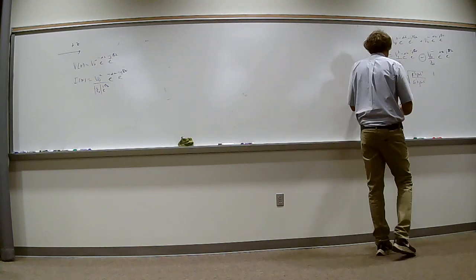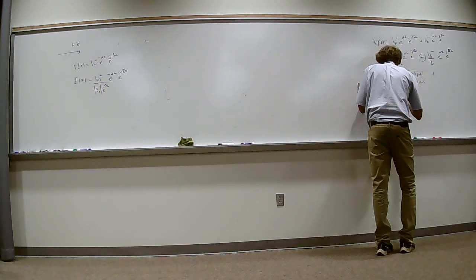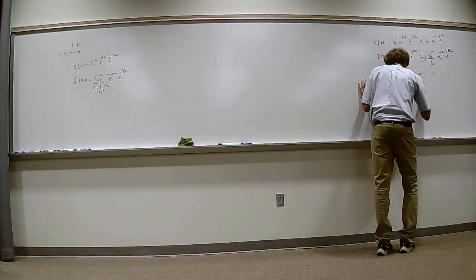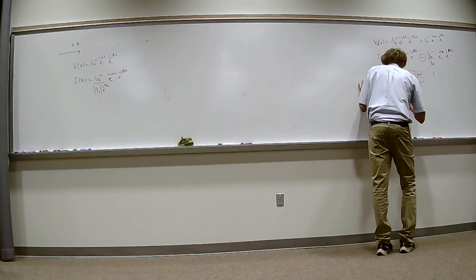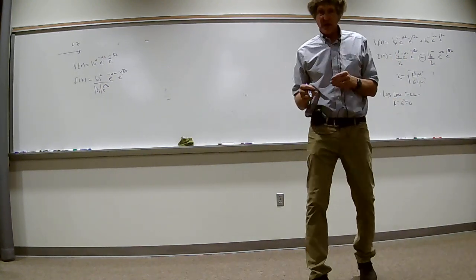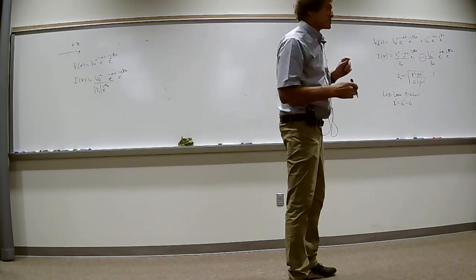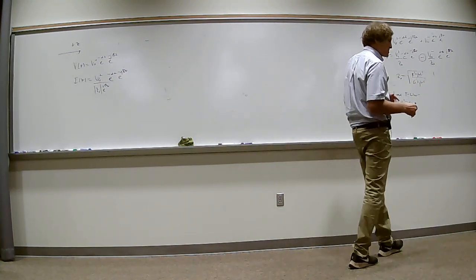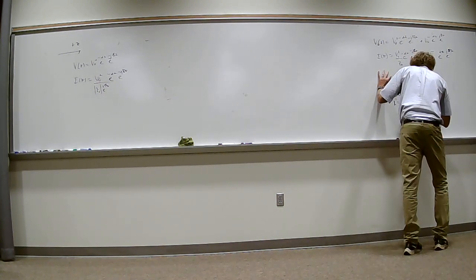Now, I might as well add this right here. If you have a lossless transmission line, a lossless T line means R prime equals G prime equals 0. There is no resistance there to dissipate power. You all follow me? If there's no resistance or conductance there to dissipate anything, then the characteristic impedance becomes what?